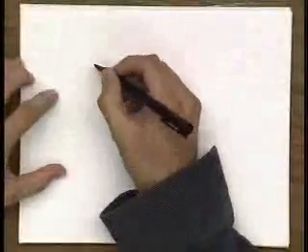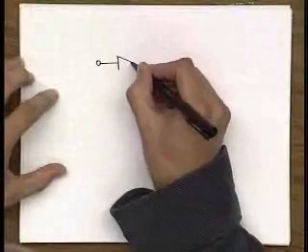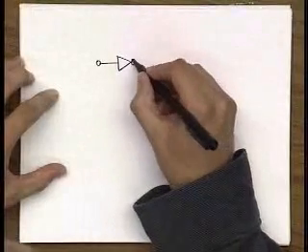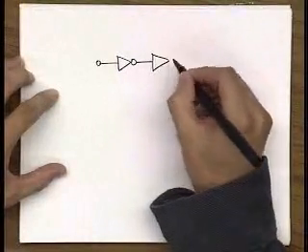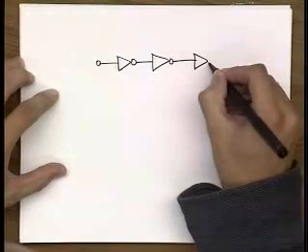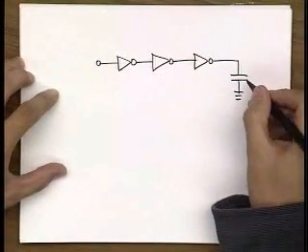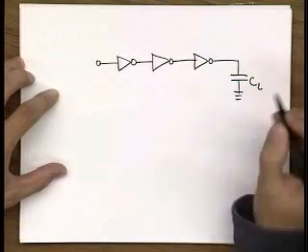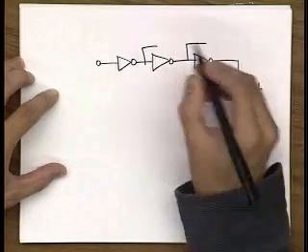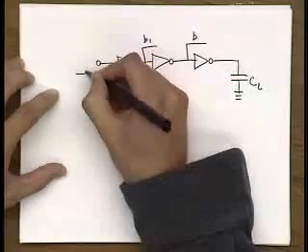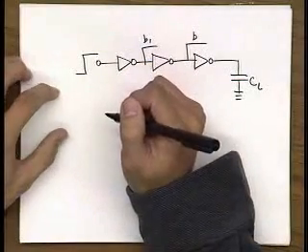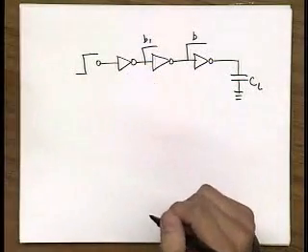So for the SPICE verification, what we normally did so far in the lectures for the hand analysis, which was perfectly valid to do, to just get the first order estimates of the important parameters that influence our delay. So we normally assume a step function at the input, but that is unrealistic in real circuits.